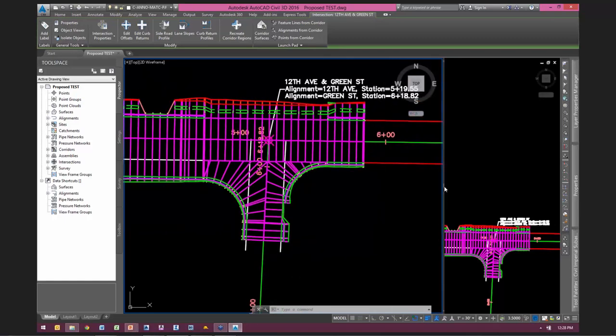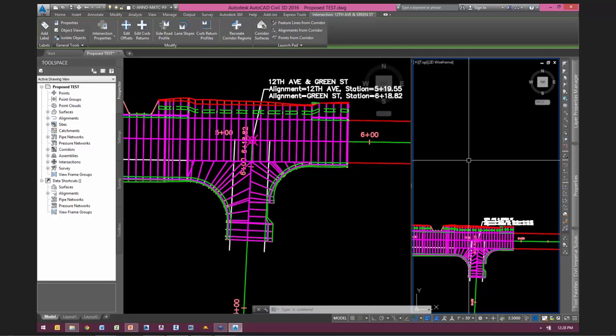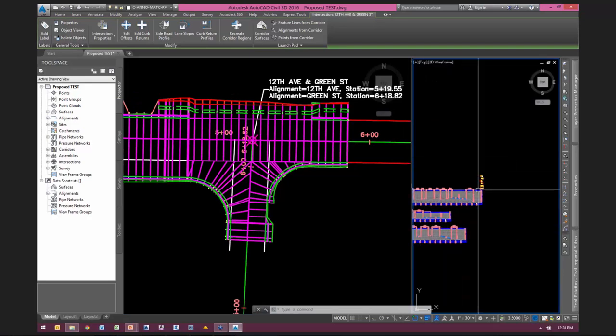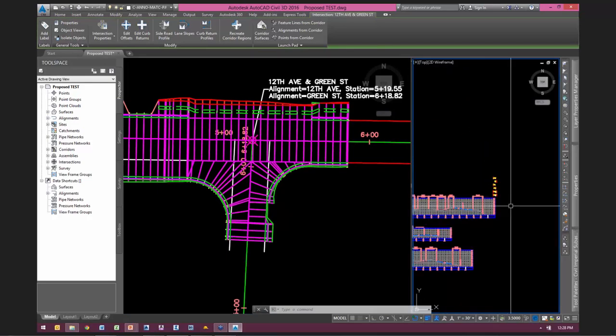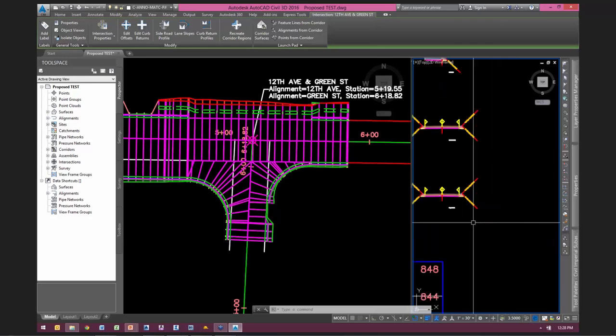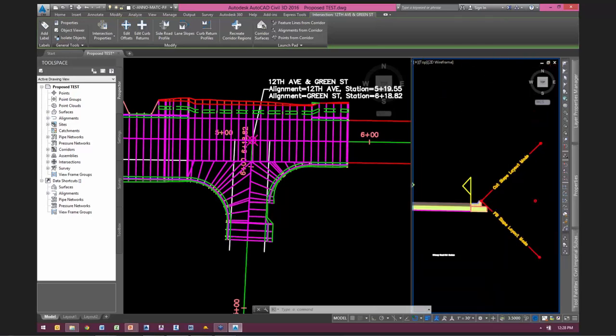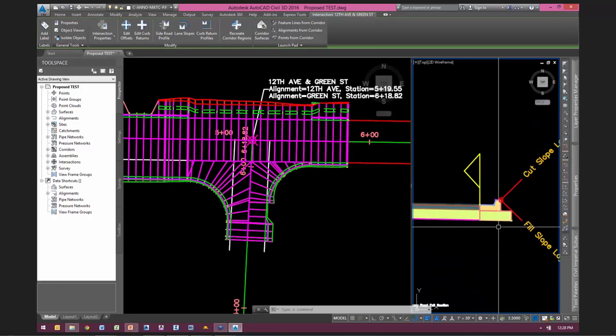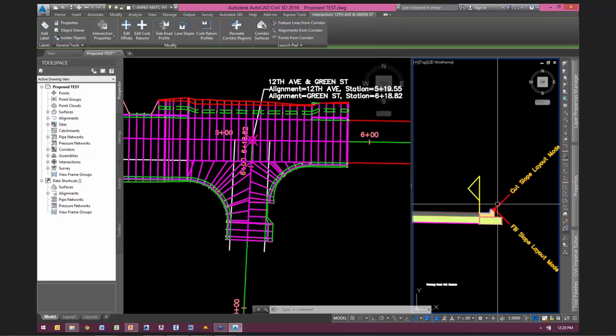And we're going to understand what we have here, and we're also going to fix up those assemblies. So when you run the intersection tool, it brings in a whole stack of assemblies, puts them at the top right of the extents of your drawing. And what comes in out of the box is a basic lane with a curb, and a basic cut fill with a ditch option, daylighting subassembly.